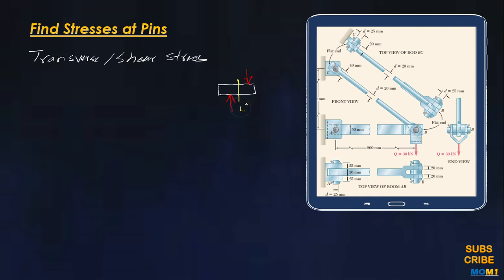Now at this phase there is going to be the shear stress, and we can calculate this shear stress as tau is equal to force upon the area. Now area in this case is parallel to the applied load.